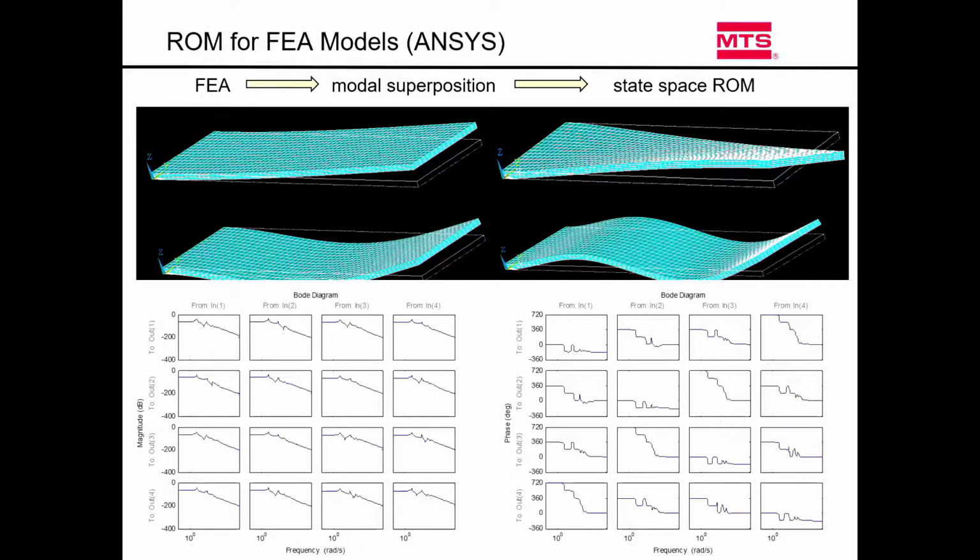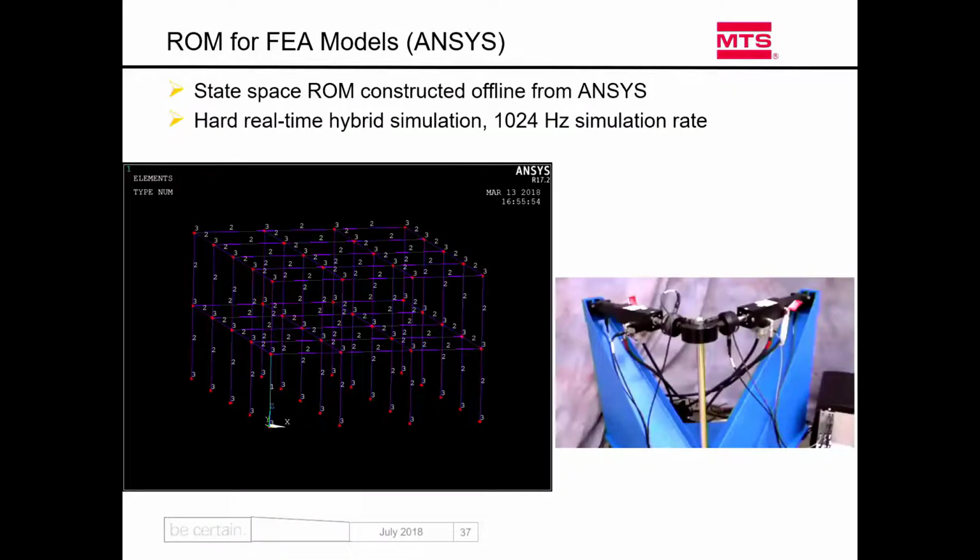What it does is that you have a FEA model, you do a modal analysis, and you get all the modes of interest. Maybe the first 4 or 5 modes, or whatever number of modes you want. Then this can be converted from a FEA into a transfer function matrix. Because you are only interested in the global dynamic modes, I'm not going to care about the stress and strain, those things. So we can convert from the FEA model to a simple transfer function matrix.